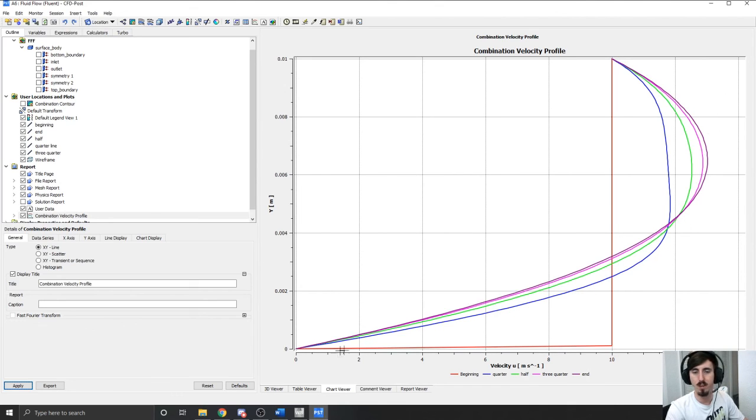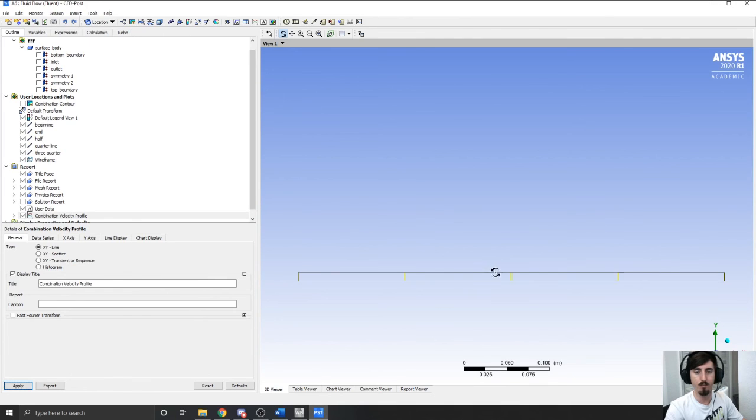You could make it stationary, and then see a Poiseuille flow, and see a perfect parabola or close to perfect parabola, and then a Couette flow. If you remove the velocity inlet and turn that into a pressure gradient, so there's no initial velocity, just the velocity of the plate or the top wall, you'd see that move linearly. So that is pretty much all we have for that.